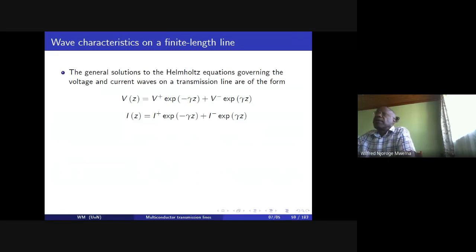So, lines are rarely infinite. Even the Kenya power lines that we get power from Kindaruma up to Nairobi substation or any other substation can never be described as infinite. Because at the frequency at which Kenya Power is transmitting power, that is 50 hertz, can you quickly compute for me the wavelength of such a signal, given that the signal is propagating through air?